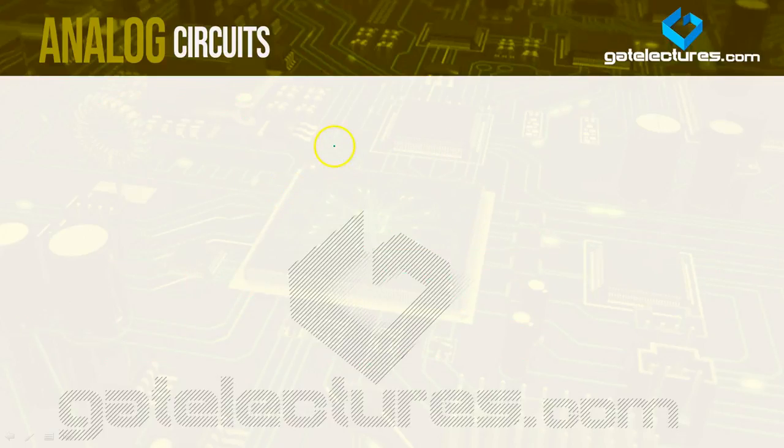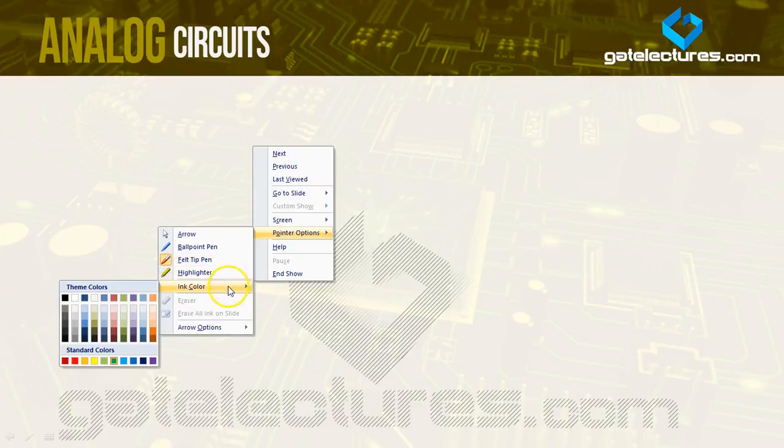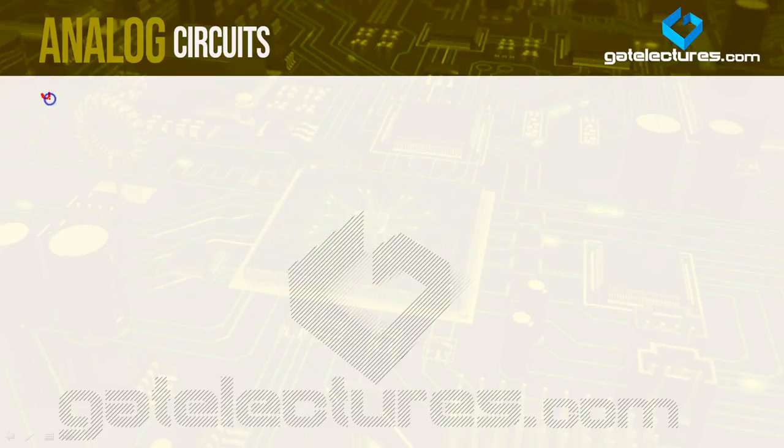Now let's discuss another subtopic, the fourth one, which is the angle of conduction. When we discussed the half wave rectifier without the capacitive filter, the angle of conduction that we concluded was equal to 180 minus 2 theta, where theta was sine inverse of V gamma by Vm, and V gamma is the cut-in voltage.